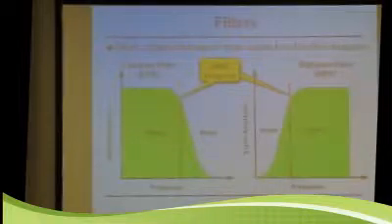We can have a situation with a high pass filter where we have, for some reason, lower frequencies. Maybe we're using a frequency multiplier, which is used in many radios, and so we multiply the frequency on purpose. We want to pass the higher frequency and stop the lower frequency. So again, you can create filters that are low pass or high pass, or you can create band pass filters, where they will pass anything essentially between these two orange lines here, and attenuate or try to stop anything on the outside of that.